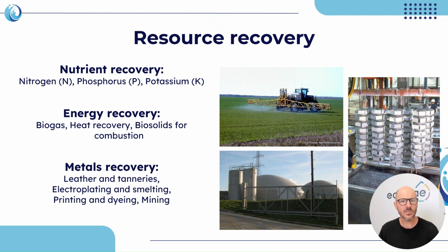Locations with certain industries are also often the targets for metal recovery, such as the leather and tanning industry, electroplating and smelting, printing and dyeing, as well as the mining industry. These activities often see wastewater discharges with higher than normal concentrations of different metals that can be recovered. Removing metals can improve the environmental health of receiving waters and water reuse opportunities, particularly in agriculture, where high metal levels may affect soil and plant health.